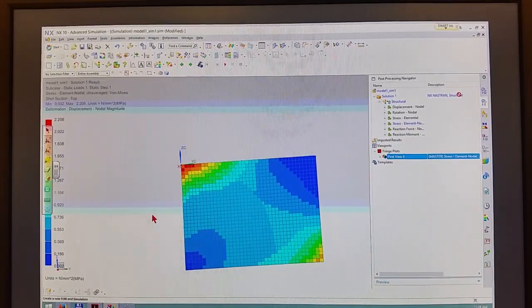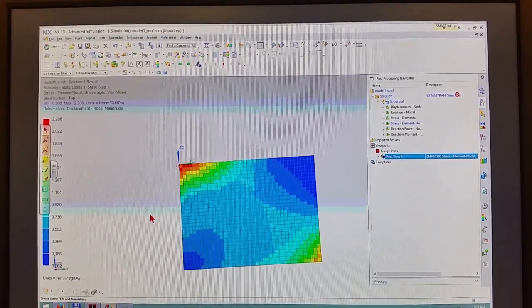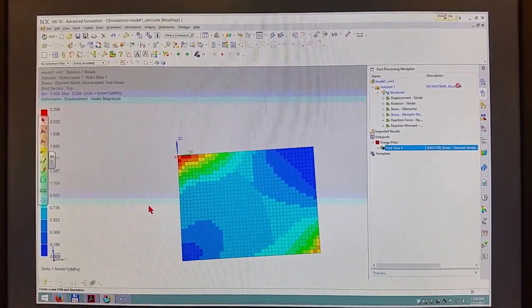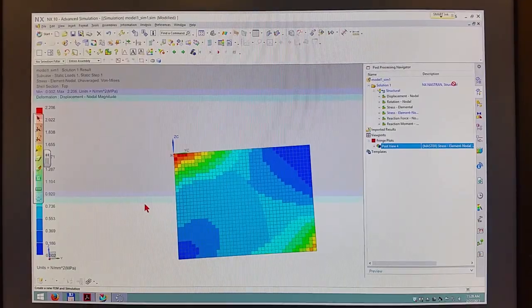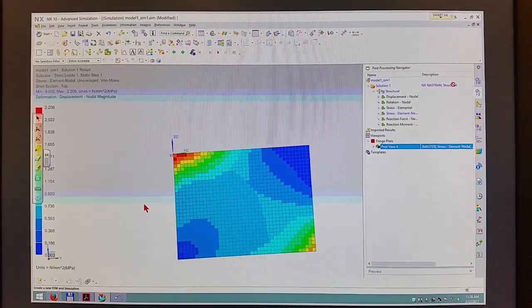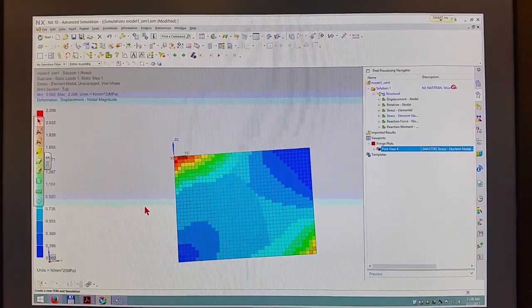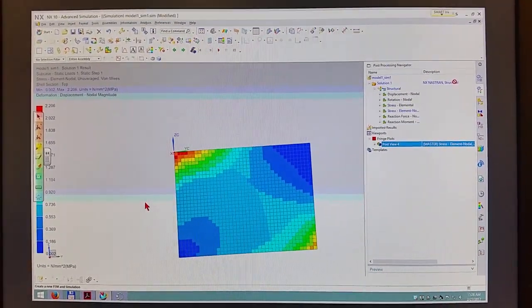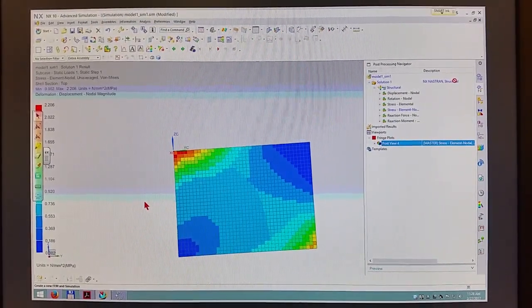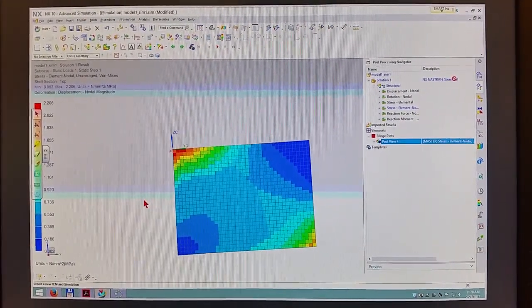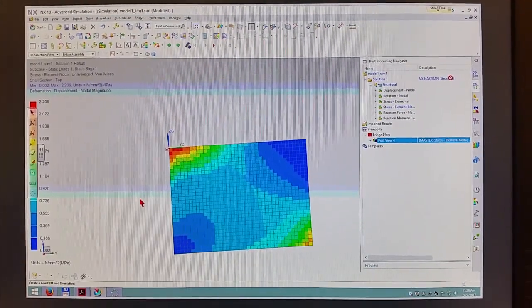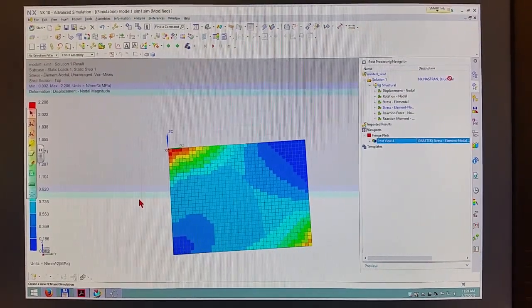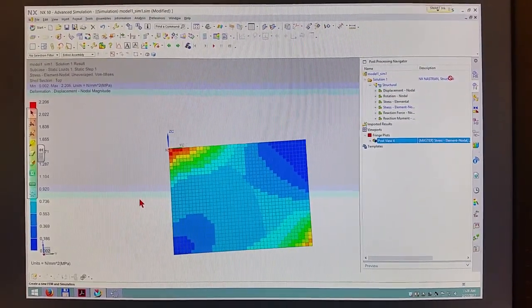It is just averaging, but again, technically I should have infinite stress there. If we were solving the equation, only because it's graduate level mathematics, where you actually start defining the correct equations for stress and strain as a function of x and y, we would learn from the stress equations that the stress there is going to be infinite, and it's a problem with the equation.